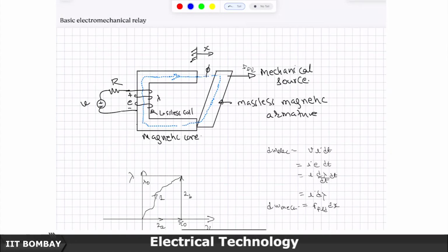So, what I have got here now is a V voltage source connected to a coil with a resistance R. The induced EMF is shown as plus minus E. Look at the polarity clearly, same as equal and opposite to V. Of course, you have to adjust for the RI drop or the current which will take place here.